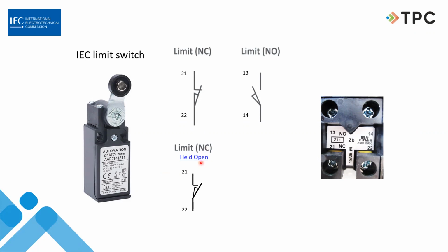You have to understand this, because if you don't catch that, you could wire it wrong and cause yourself a lot of damage. And of course, then we have a normally open switch held closed. That means something's on it, pushing it closed. So when you're in a hurry troubleshooting, make sure you pay lots of attention to this.